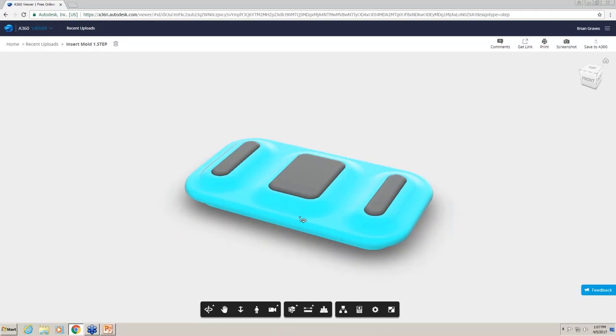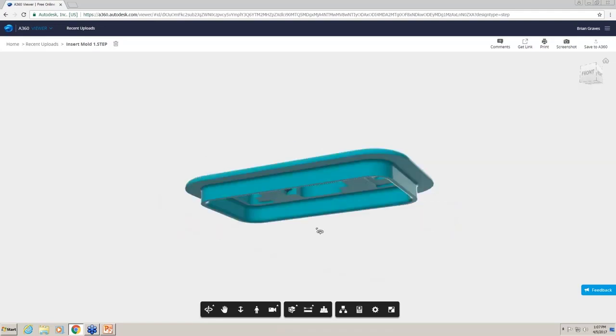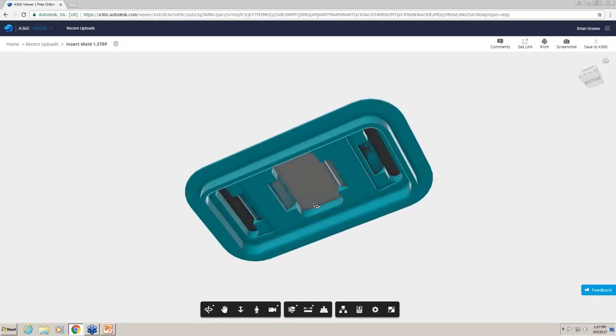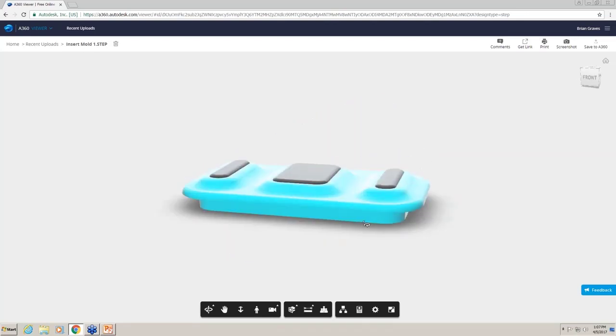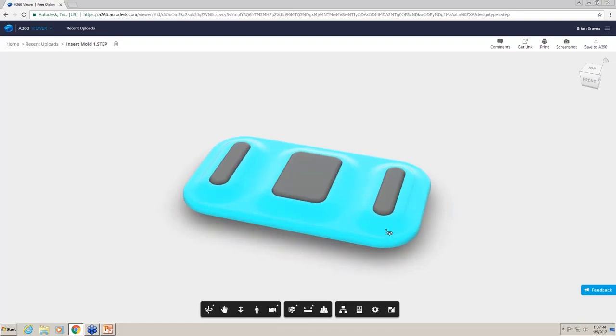We talked with our designer or engineer on this project, and we actually came up with a solution to use side actions or hand loads to pinch this insert, and then we were able to figure out a way to run this in a horizontal press. Very complex insert molding process, but we were able to formulate these into the process, and we had success with it. We'll talk a little bit about this more in the rest of the slide.